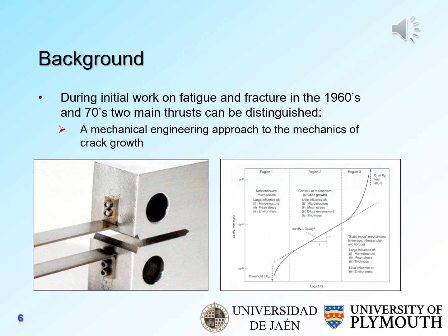The second approach is more of a mechanical engineering approach to the mechanics of fatigue crack growth, and that ranges from things like the experimental measurement of crack growth using, for example, crack tip gauges that you can see in the picture, to Paul Paris and his da/dN versus delta K relationship. This really reflects that there were two sets of people working on fatigue and fracture in the early days: metallurgists, material scientists, and mechanical and civil engineering.